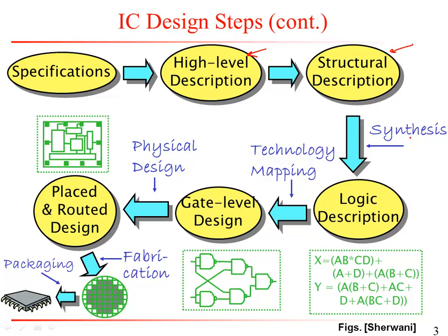This step is usually called synthesis, and it's done automatically. I mean, it wouldn't be reasonable to expect people to do this step. And the logic description could be generic, so you could specify your system as the AND of 10 inputs, and that doesn't care if you have a 10 input AND gate in your library or not. It's just a way of describing things.